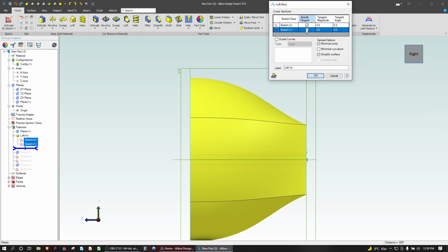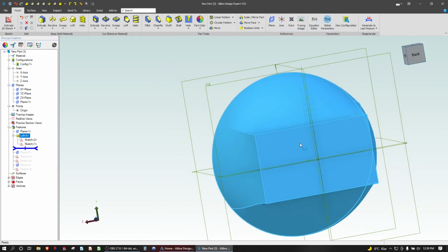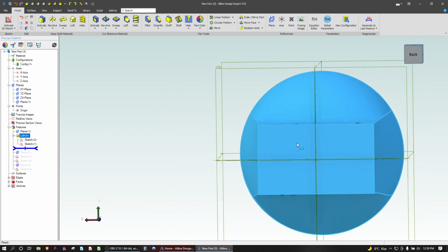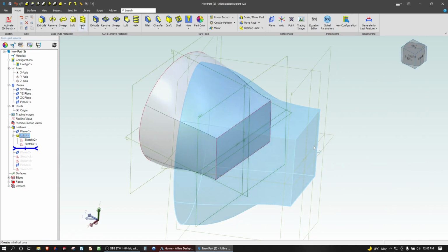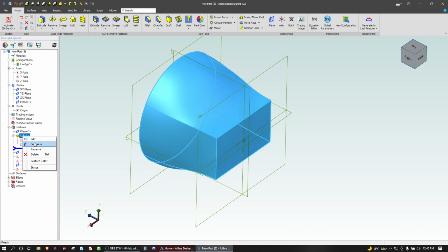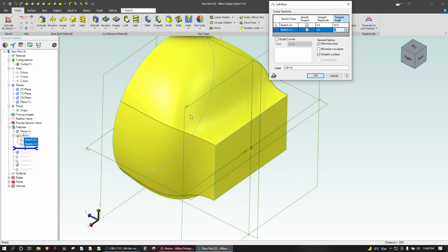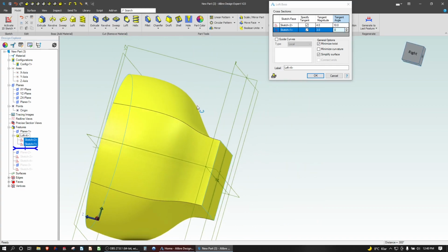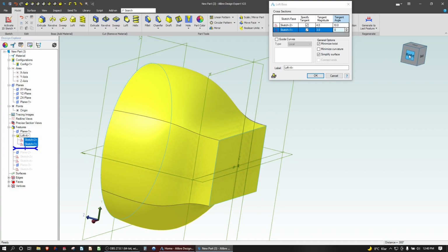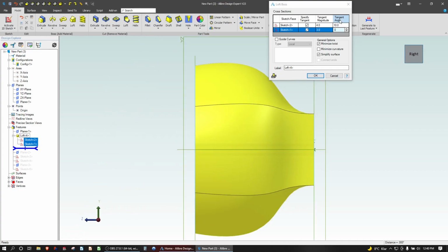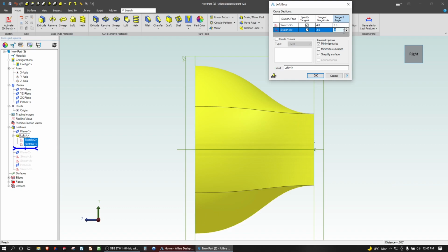We can also say specify tangent on this end, and we'll say like 3. And there we have very, very simply generated geometry. If there's anything left to cover, let's edit our loft here, and we're going to say tangent angle, right? So this changes our tangent angle a bit, right? If I add 10 degrees here, you can see how much that affects our profile. And if I go normal again, we're going to say back to 0.